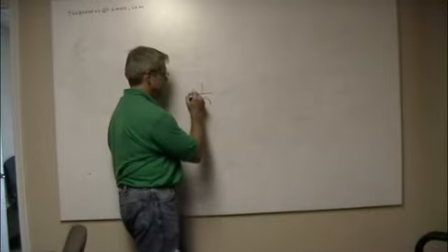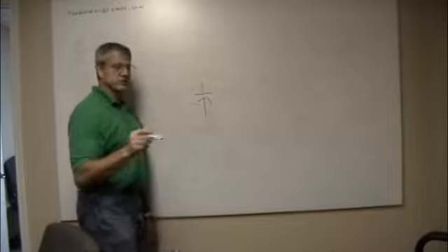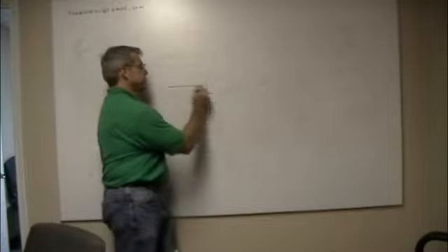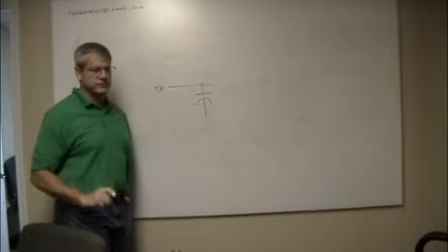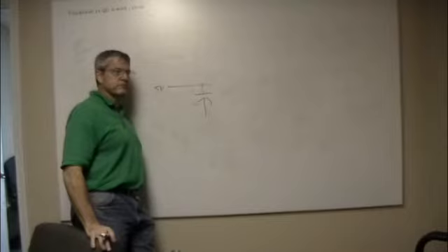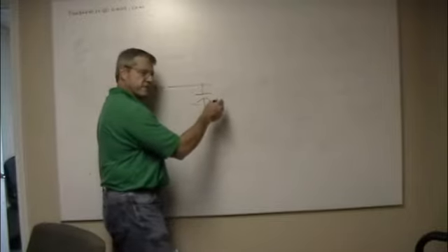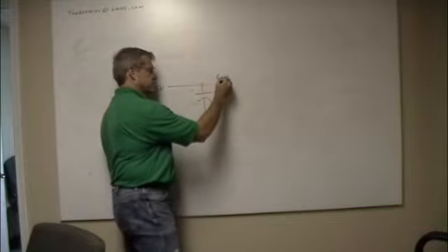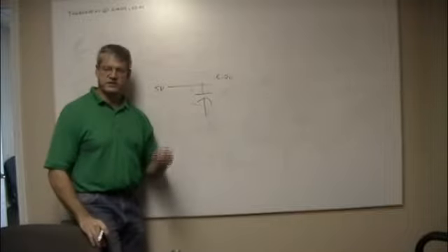Your capacitor has a voltage rating. De-rate them. So if you're using 5 volts, go anywhere from 20 to 50% higher. So you don't want to use a 5 volt capacitor. You want to use no less than a 6 to 7 volt, and go higher if you can, if it fits in your space.